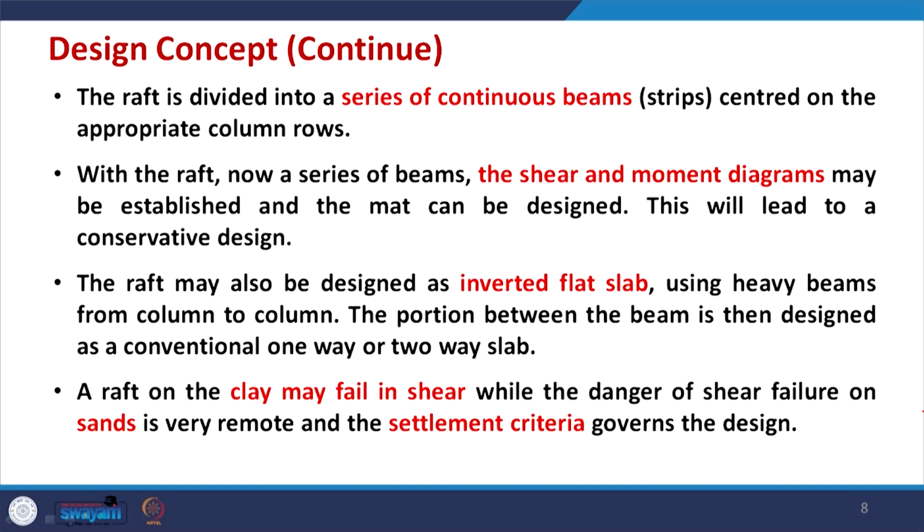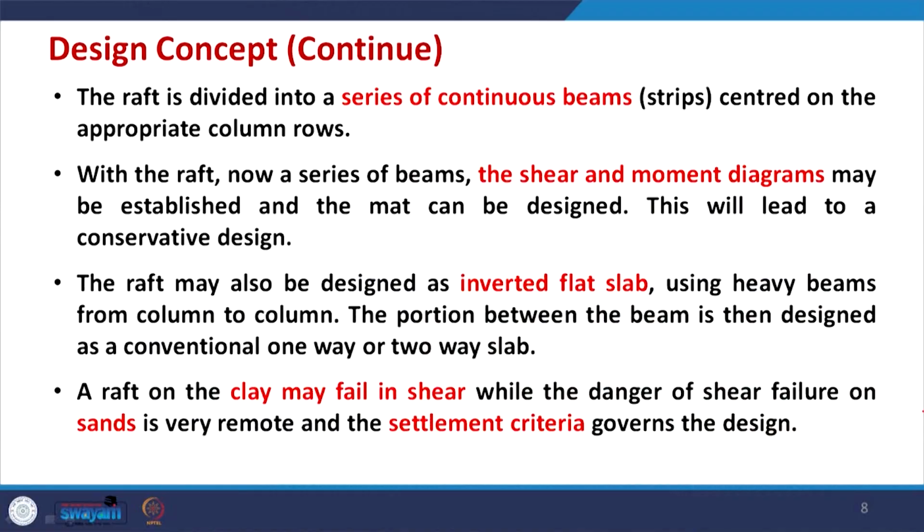Then there is a difference when you design the raft foundation on clay soil and on sand. A raft on clay generally fails in shear, while the danger of shear failure on sands is very remote and the settlement criteria governs the design. So, when you design the raft foundation for clay soil, your shear criteria will govern the design, but when you design the same thing for sandy soil, then settlement criteria governs the design. So, with this let us talk about the settlements in rafts.